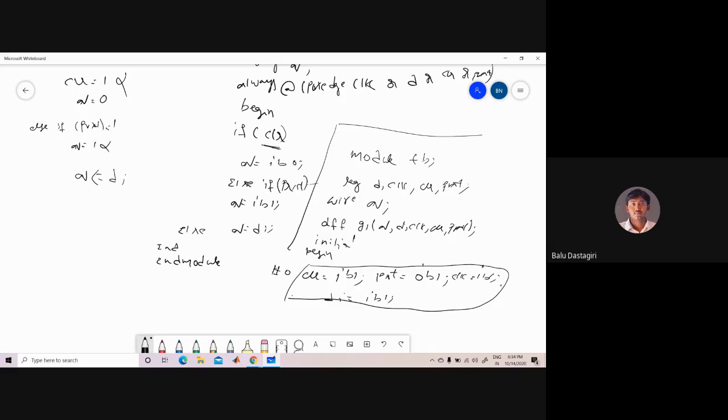So when you are writing the test cases, you forget about the logic that is written in the main program. The logic in the main program is that the clear and preset should not be active at the same time. Any one of them should be active at a time. If you make both clear and preset active here, it will take only the thing related to clear.